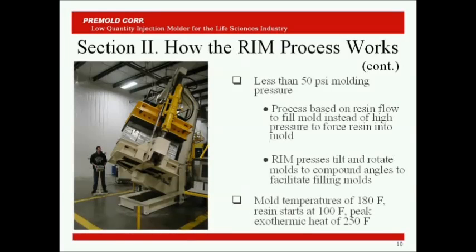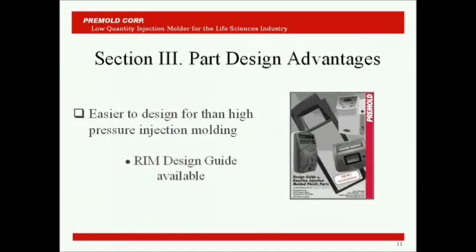Thank you, Ken. As we've discussed, reaction injection molding is a design-generous process with far more design freedom than high-pressure injection molding or pressure forming. This is because RIM parts are much more resistant to sink and warp.